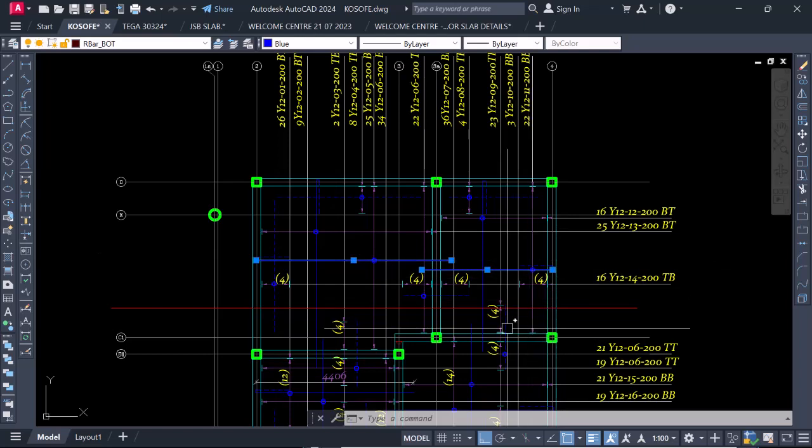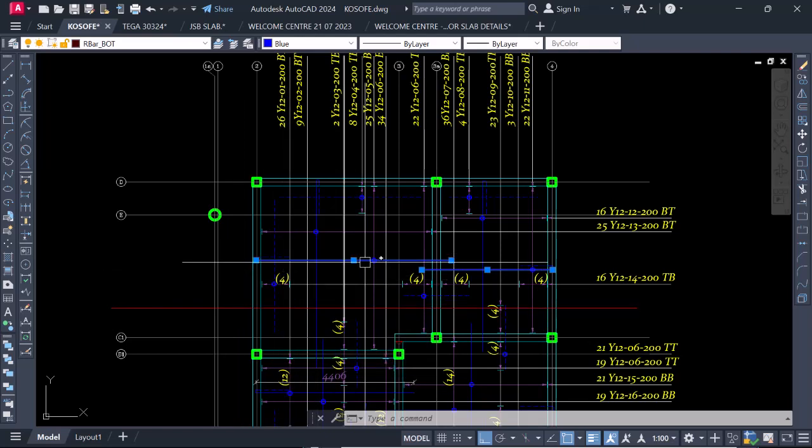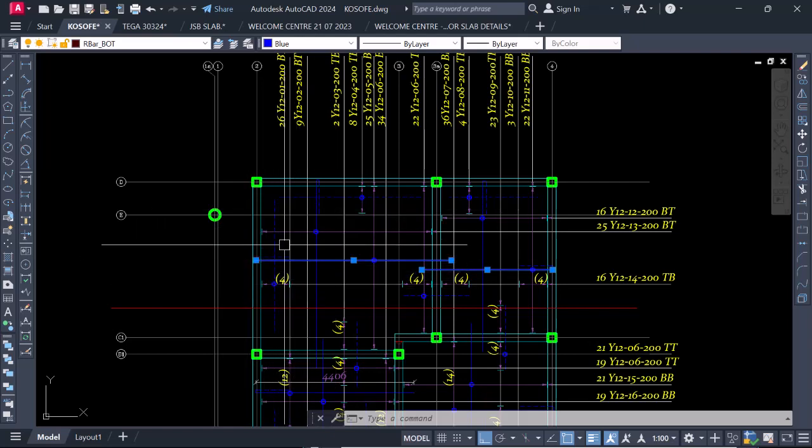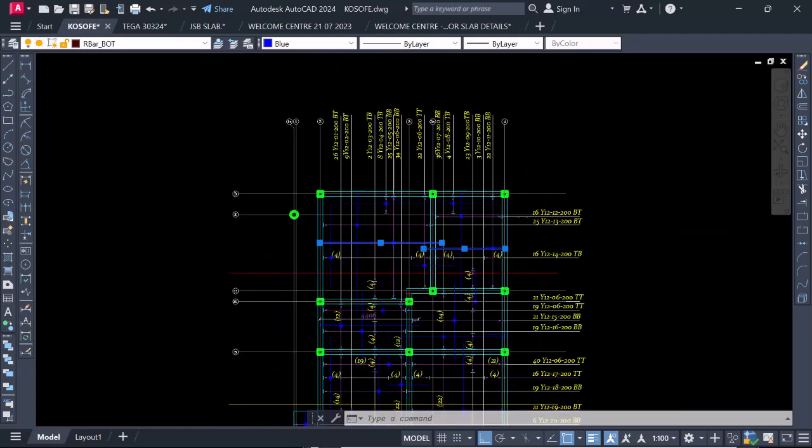All right? I hope there is no confusion. But listen to me. Look at this rebar here. We return it and we call it 5. So both the bottom, we call it 5. So this little return, we're going to specify it to be 11. If you feel that there is going to be any confusion, what we're going to do is to terminate it and not include it. But for the purpose of our detail, it is very, very simple. So we can make this the same 5 for the top bar, and here will be the same 11, and here becomes 6.